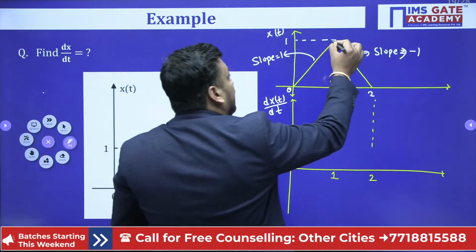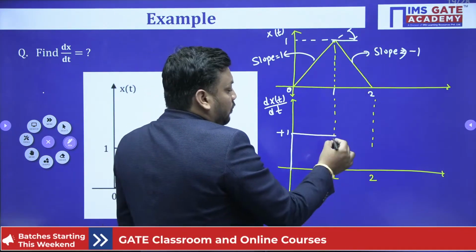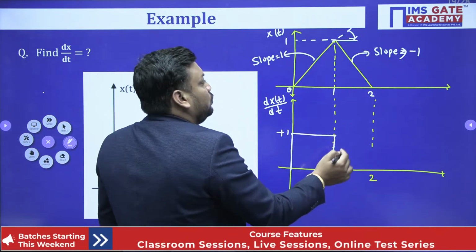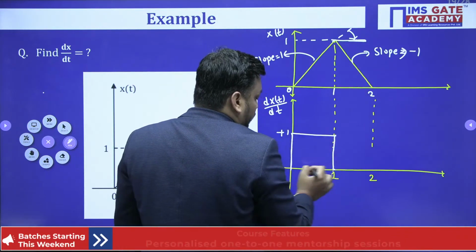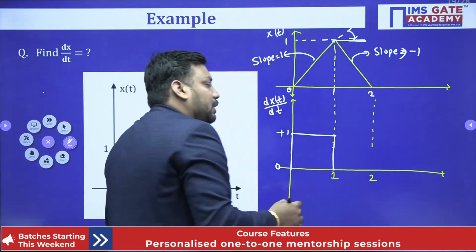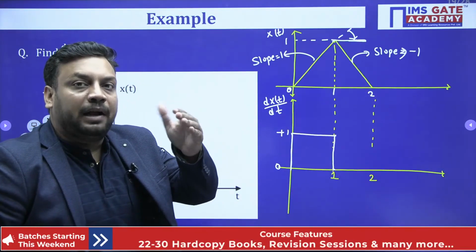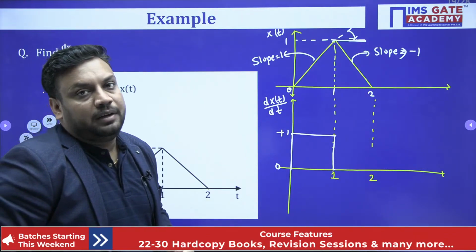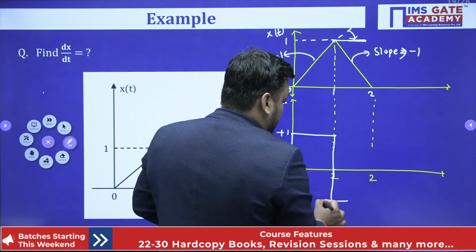After that, student, this line is going downward, and constant line differentiation is 0 only. So when you reach this line, you already reach the 0 value. Now what is the slope of this line? Minus 1. While differentiating, the slope of the ramp becomes the magnitude of the step, and this time the slope is minus 1, so we should draw a magnitude of minus 1 only.